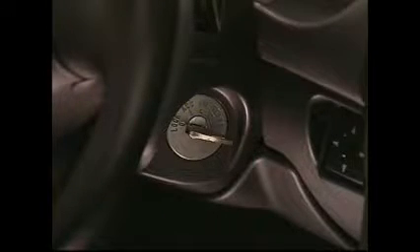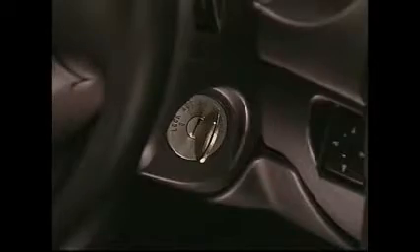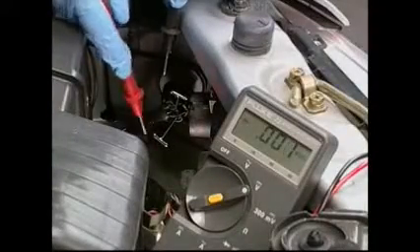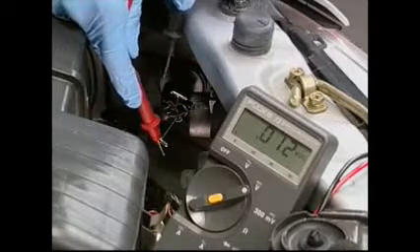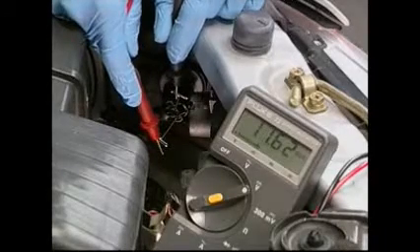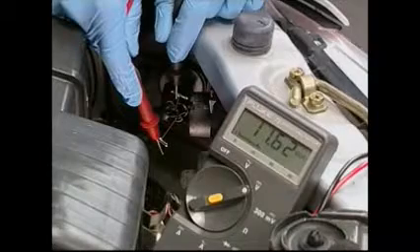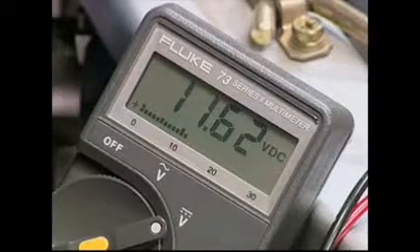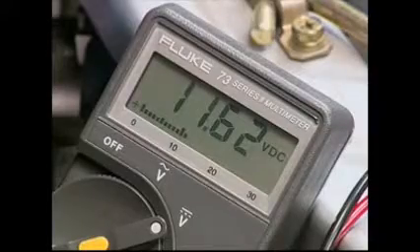In order to do a voltage drop test, current must be flowing through the circuit. In other words, the circuit must be live. As we saw earlier, to do a voltage drop test, you test the circuit with the red probe at the point nearest the voltage source and the black probe on the point nearest the ground. The display will show the amount that the voltage drops across the load.